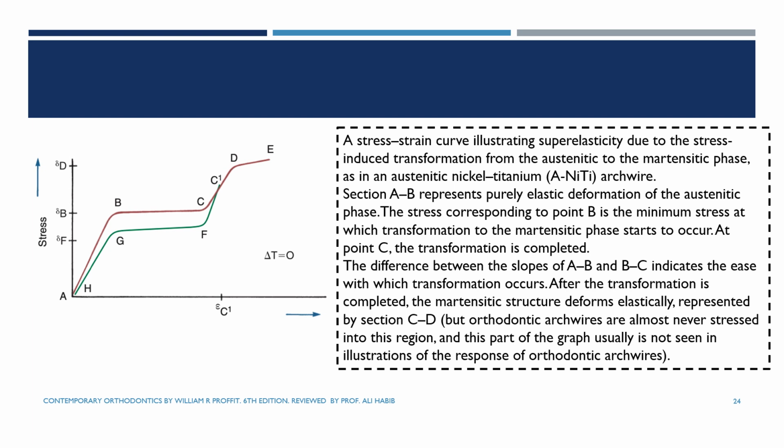But another important feature that I would like to talk about is that these wires, the A-NiTi and superelastic wires in general, have a loading curve and an unloading curve. In other words, the level of force that you need to load this wire onto the brackets is higher than, or different from, the force or load that is delivered by the wire on the bracket, which we call the unloading curve.